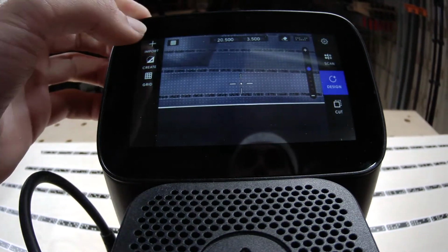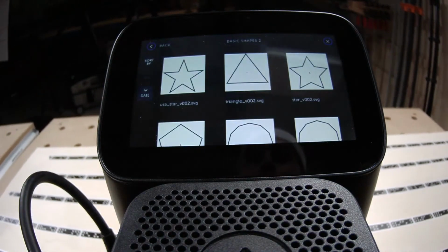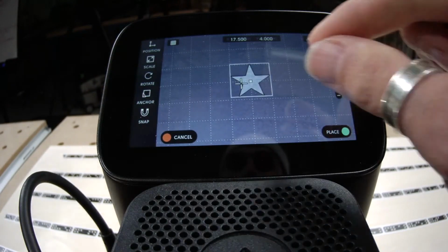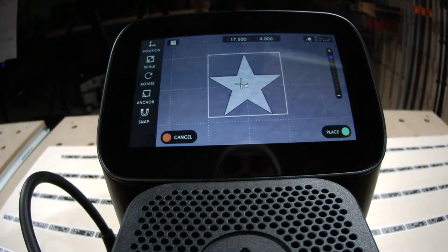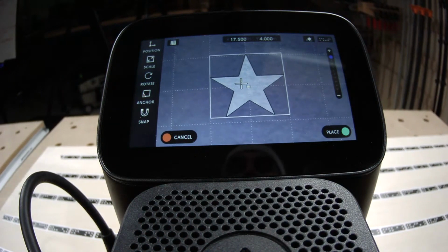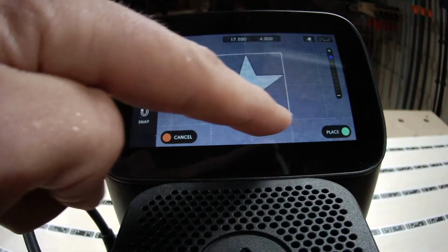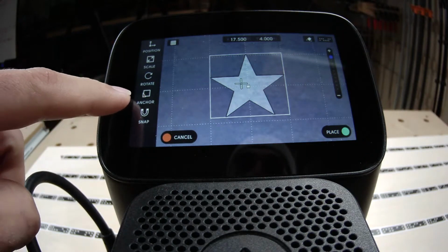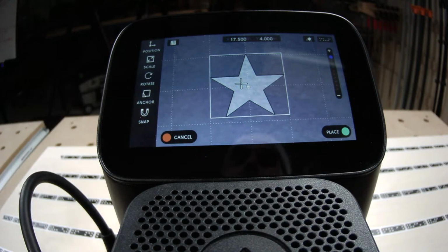Custom anchors, we're going to show you one cool one here, and Sam's going to talk about it while I import it. So here's an American star, which you guys are very fond of. Previously, our standard anchor points would have the center be the geometric center, sort of the center of the bounding box. And that's not actually the rotational center of the star, so it would always be quite frustrating trying to place that exactly where you wanted it. So now that custom anchors is a thing, I've updated the project on Shaper Hub. I think it's called Basic Shapes. If you search for Basic Shapes, you'll find these to take advantage of.